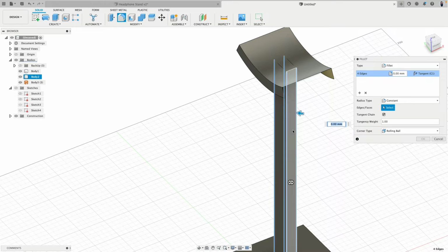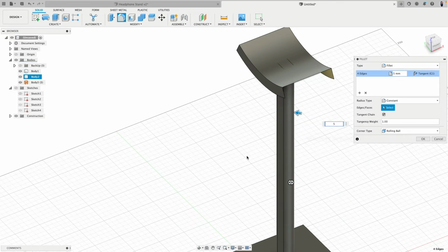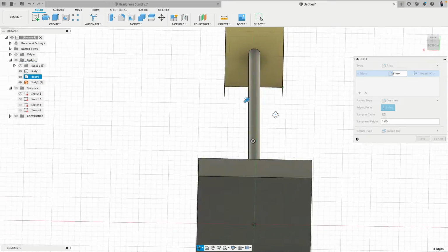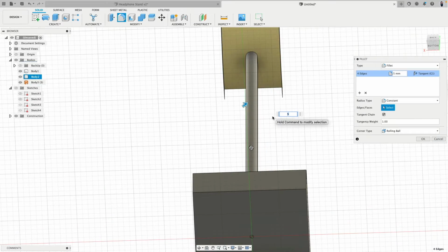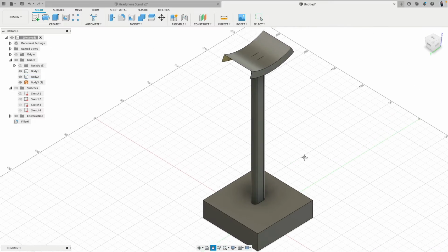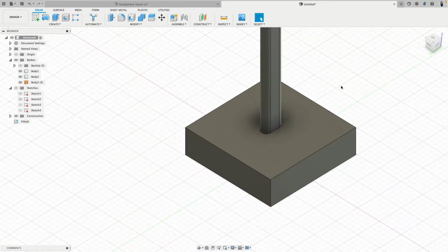Now this is 10 millimeters, which means I can do a fillet of 5 millimeter. And then you see I get perfect half rounds. If I do 4 or 4.5, you see it's not really perfectly round. And 5, no, 10 divided by 2 is 5. There we are. Very nice. Cool. Now it doesn't look too bad.